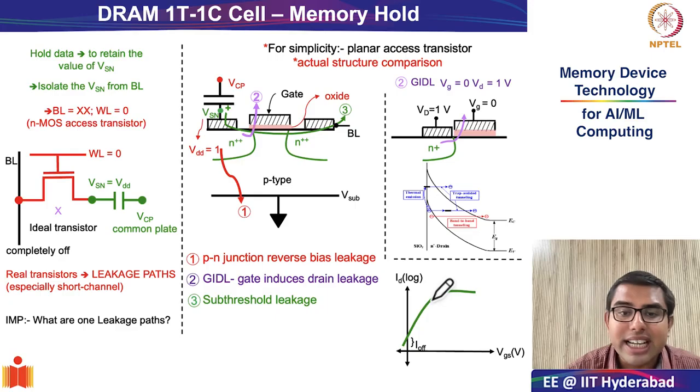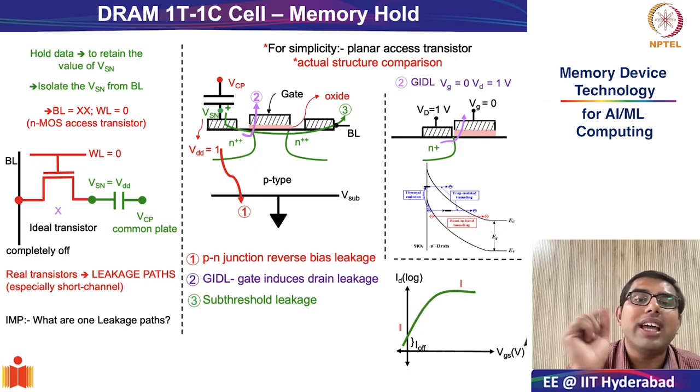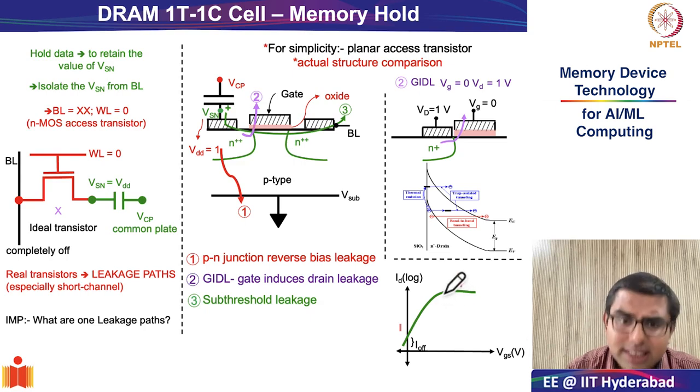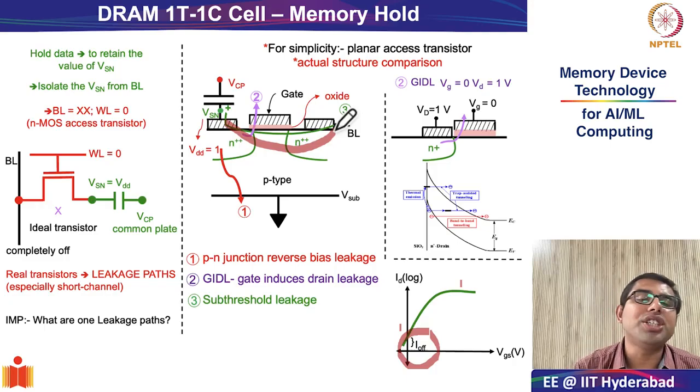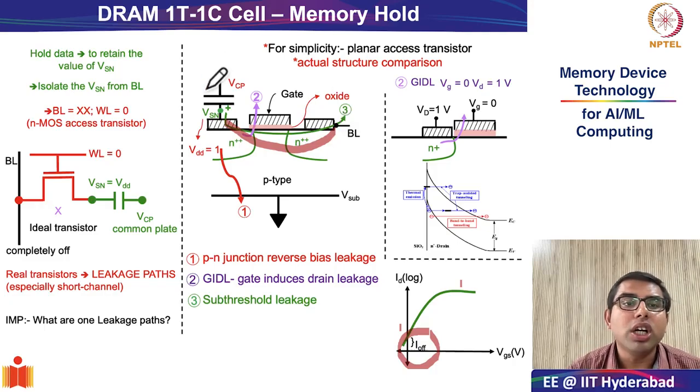Subthreshold swing is essentially the slope with which the transistor goes from the off state to the on state when ID versus VGS is plotted on the log scale. So this results in a finite off current for the N-type transistor. This finite off current, which flows as a diffusion current from the drain to source, is also responsible for leakage of charges from the storage node.